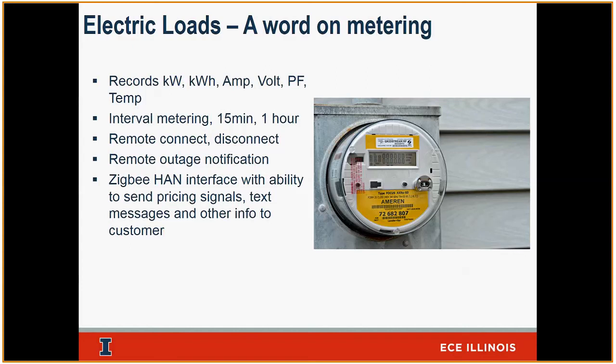But it can also report temperature, right? Yes, it can. That's basic temperature, the outside temperature, not necessarily the temperature inside the home. These typically sit outside. You can use temperatures to do some analysis, since the load varies with the temperature. Exactly. How do you correlate the temperature to the kW and build some correlation of what you expect to happen at a particular temperature in the future? So you can build a trend, say every time it was 72 degrees, the average load was X. And in the future, you can say, okay, I expect load to be this value based on the correlation that I'm getting here.